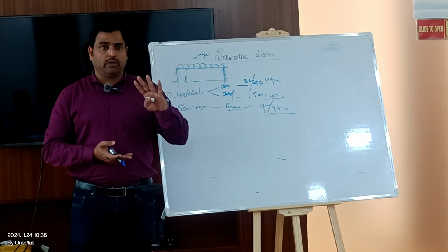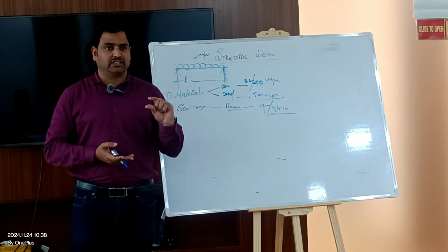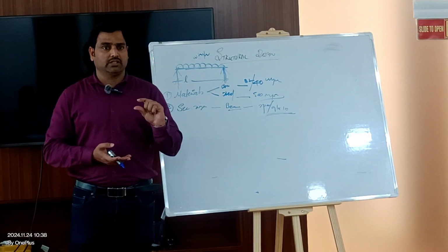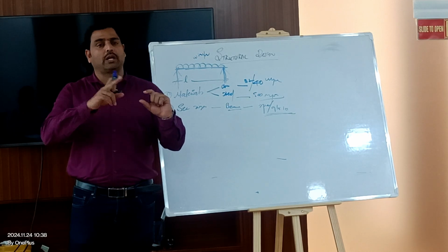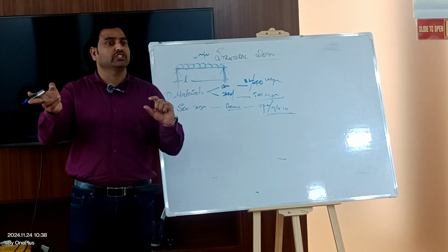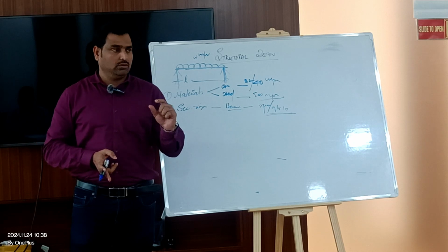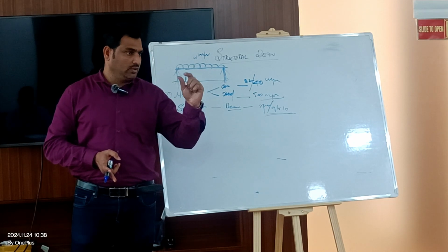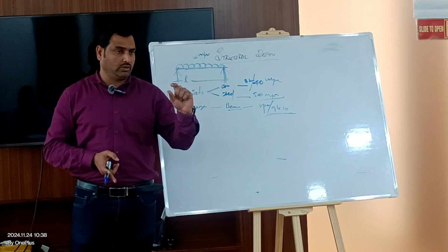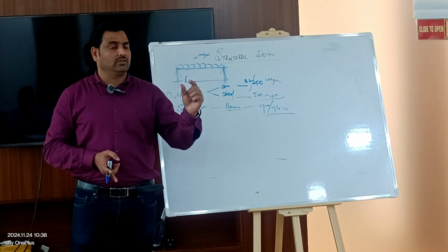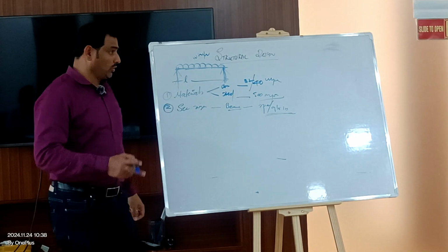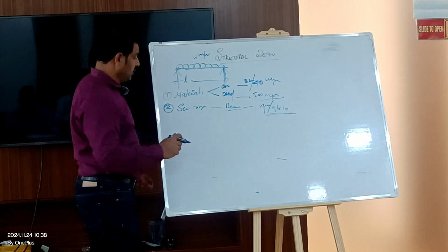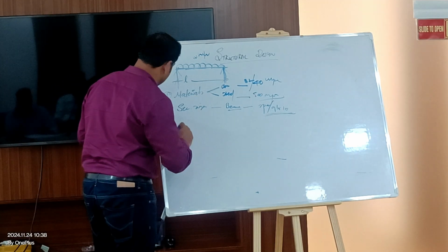If you don't want to increase by another 10 centimeters or 5 centimeters, thinking you're going to save money, you're going to waste about 2 times more money in the steel as well. So don't think of this 5 centimeter, 7 centimeter, 10 centimeters lightly. Sometimes the design will pass, but it will not pass in deflection, which is the serviceability criterion. That's what we said, moment of inertia, right? How about the third one?